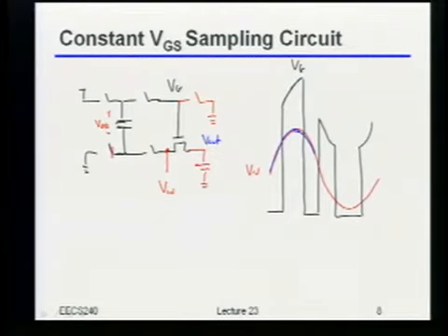Yeah, I got to be careful, right? Because this voltage over here, like you've seen, if this was up at VDD, that VG is definitely above VDD. So I got to be really careful with how I build these switches. A, to make sure they don't blow up, and B, to make sure they actually behave the way I want them to. Okay? So as an example, let's see what's one bad thing that might happen if I'm not careful.